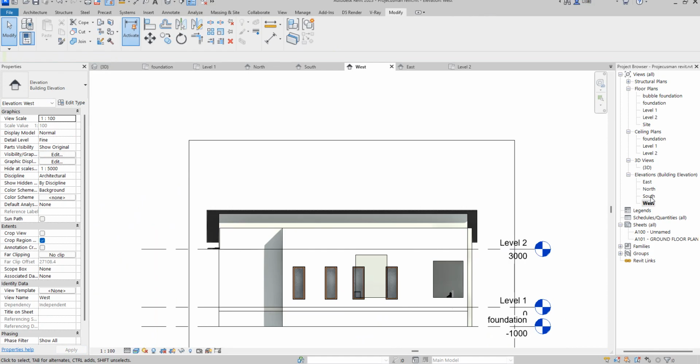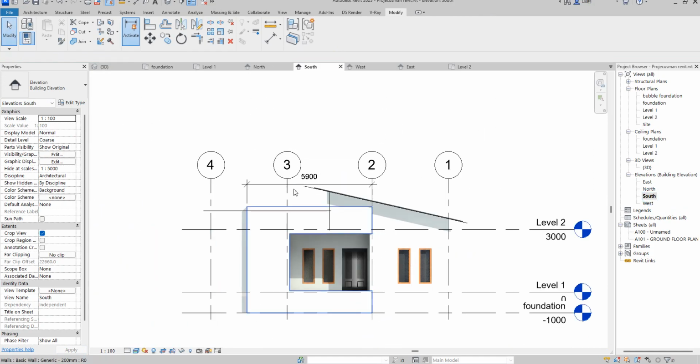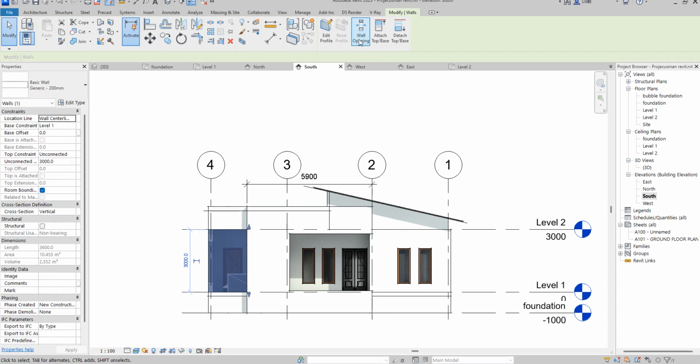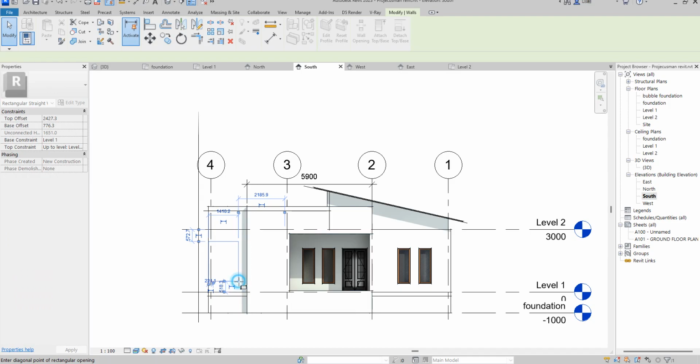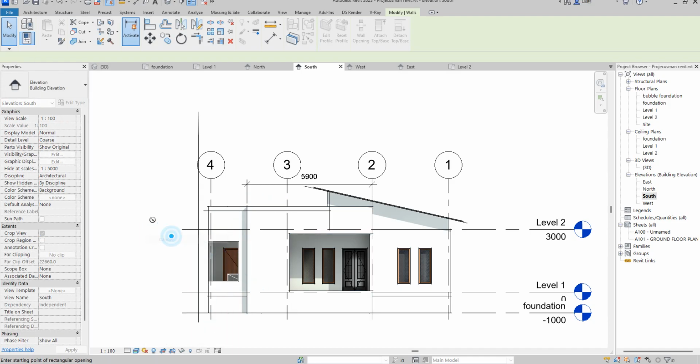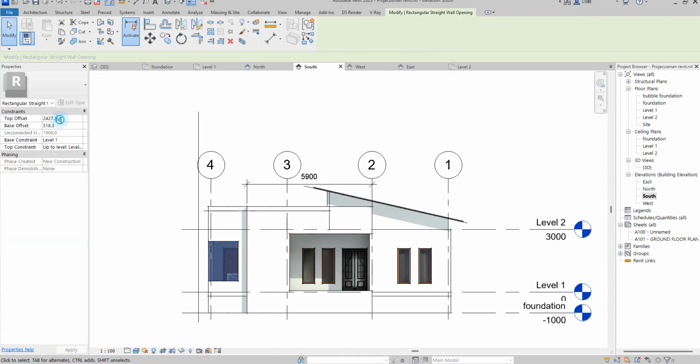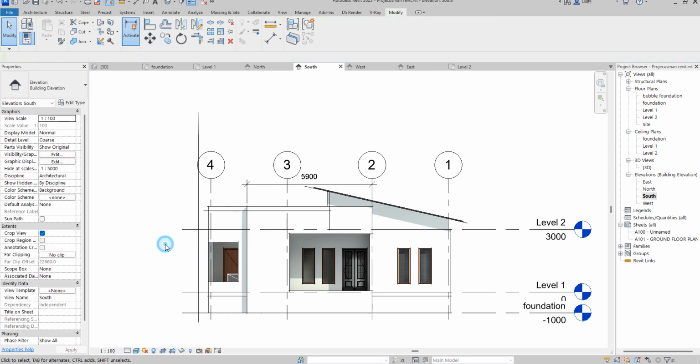So I can now go to front elevation and do the same thing as well. I'm going to go front elevation, select this wall and say open the vertical as well. So this one has given me references, so I'm going to work on that. Just click. Then what you need now is that you select this again, you do the measurement 24, then 500. I think that should be good.